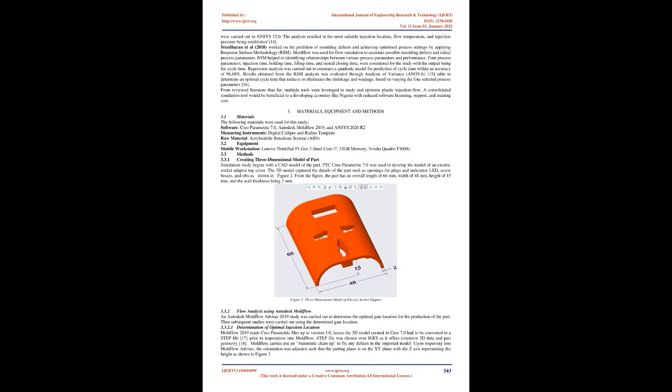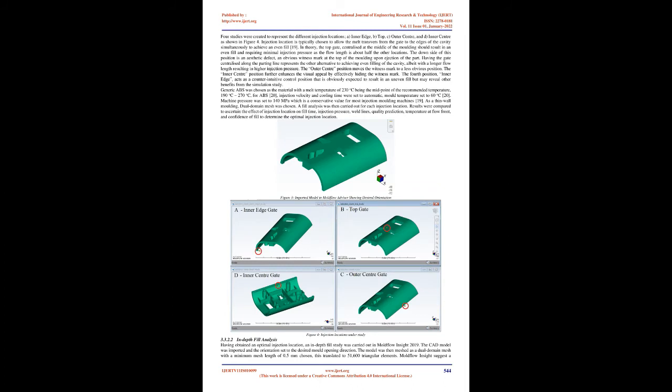9. Hussain et al. 2012, worked on the optimization of plastic injection molding parameters using the Taguchi optimization method. The focus of the study was to minimize warpage on polycarbonate/acrylonitrile butadiene styrene, PC/ABS, shine guard injection molding. Simulation of the process was carried out using Moldflow Insight software. The study was based on Taguchi's method and analysis of variance, ANOVA, to analyze and optimize processing parameters such as mold and melt temperature, packing time and pressure, cooling time and temperature, ambient temperature, and runner size.